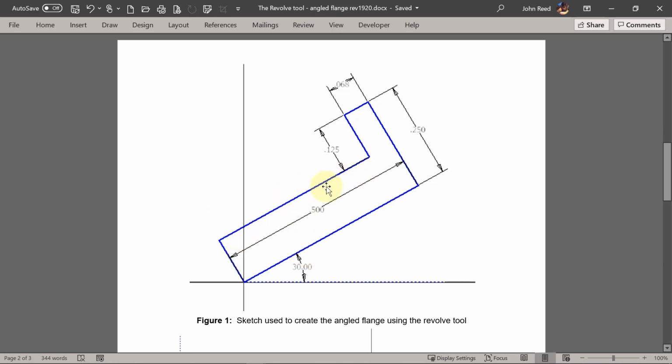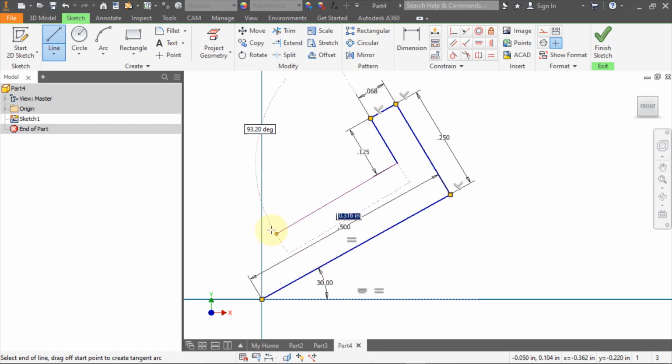This line isn't specified in the drawing, but we can infer what it is because it comes down and it matches up with the first line, and it's perpendicular to, there we go, it's perpendicular to the preceding line, and Inventor is smart enough to know that I want to go back to that particular location.